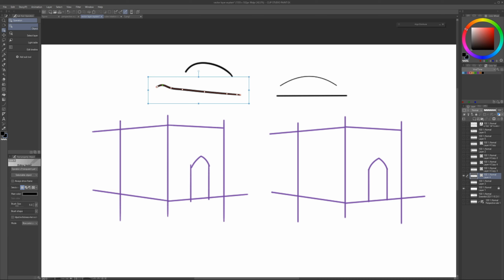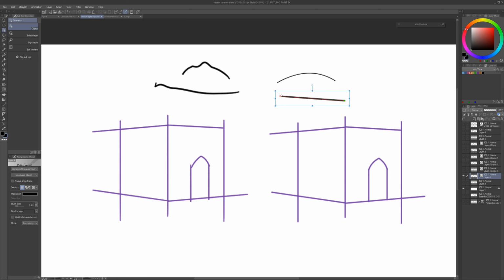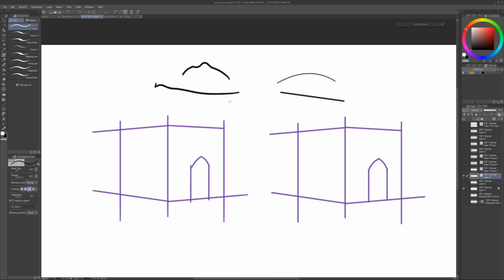However, when dealing with vector lines created by the pen tool, modifying them becomes nearly impossible due to the presence of multiple control points. In contrast, using the Straight Line tool to draw lines allows for effortless adjustments, since there are only 2 control points at each end. Similarly, with the Curve tool, we have the flexibility to change the curvature whenever needed. Relocating the line position on the canvas is also easy. Simply hold Ctrl or use the Object tool to drag the lines to the desired position.